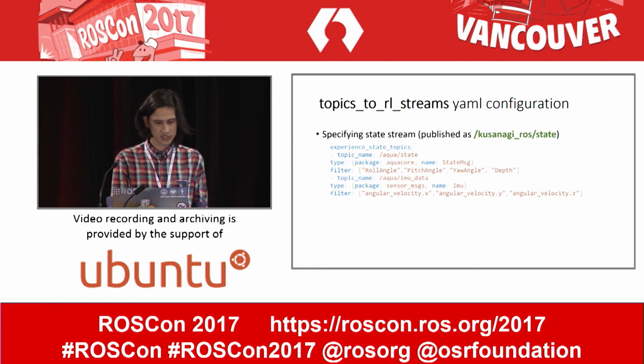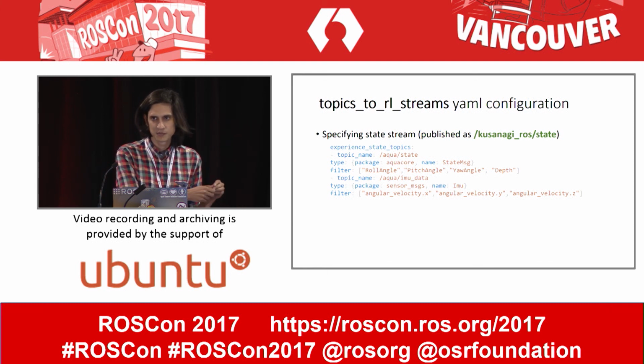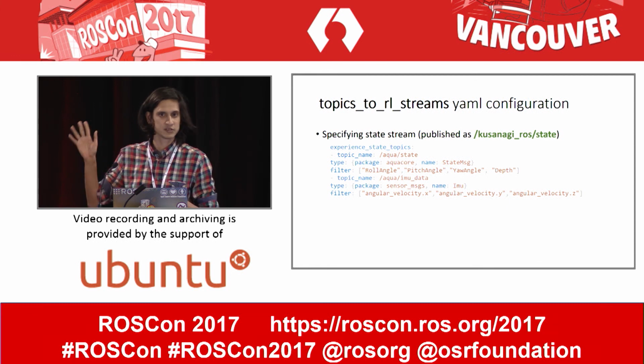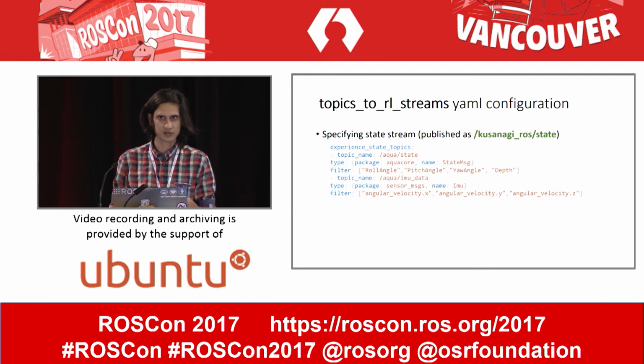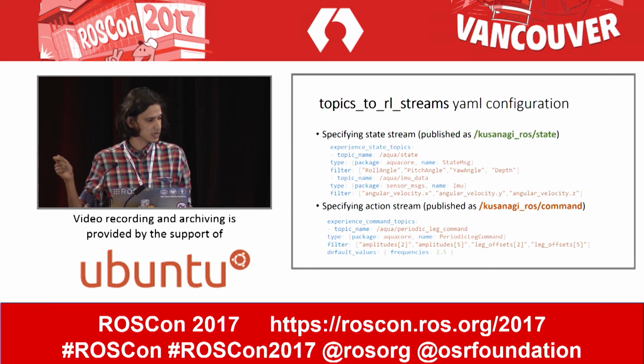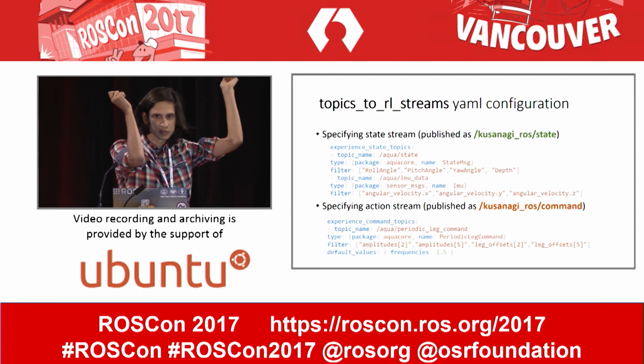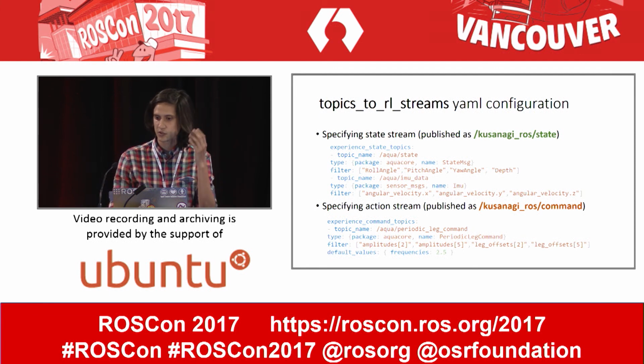Essentially, we have a node that reads a YAML file that tells it, subscribe to all these topics and put them out in some desired format, usually just a single vector. And we have a similar thing for any control command that comes from the controller: we can tell it, publish it to all these different control topics.